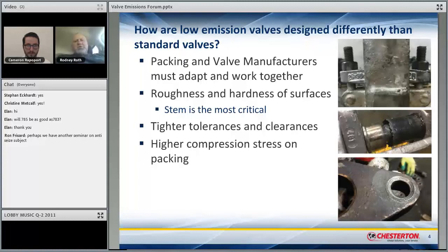And so in order to make the valves cheaper, that gland flange you see there that's bent is actually hollow on the bottom side. So that's not a solid block of steel. That's a block of steel that's approximately 1/4 of an inch thick right under the nuts, and then it's hollow all the way out to where the studs go through. And so that is a very weak component. When you start putting the load out as far as we do, that hollow portion is going to give.